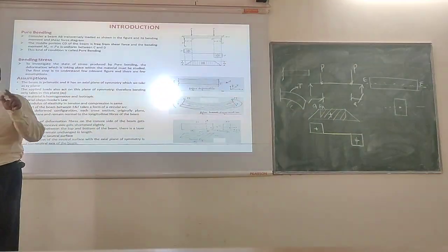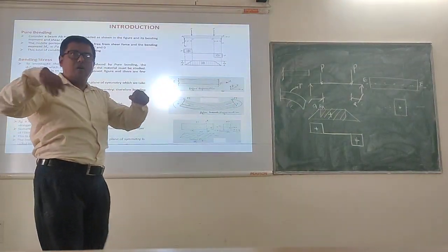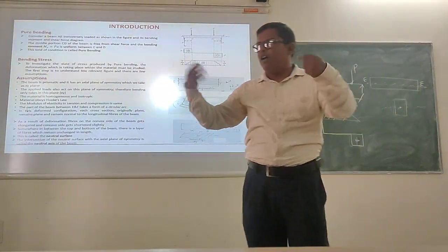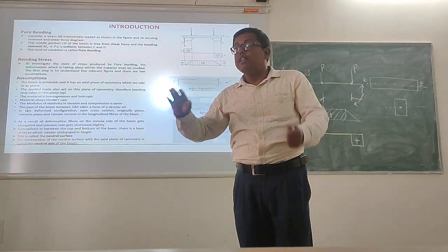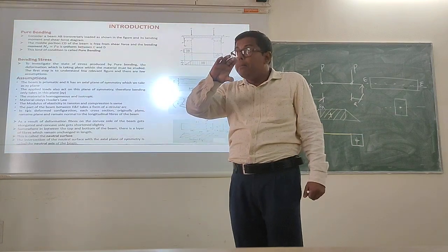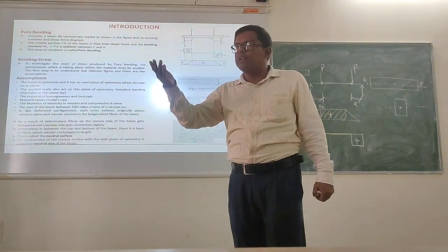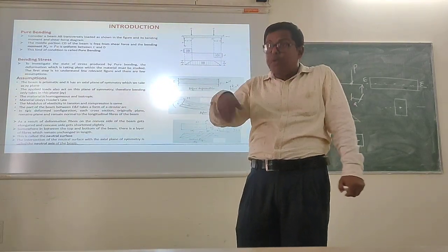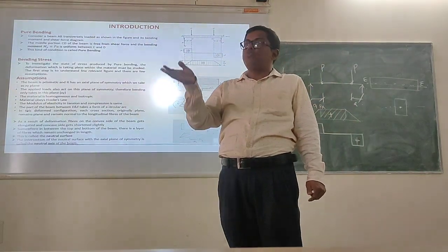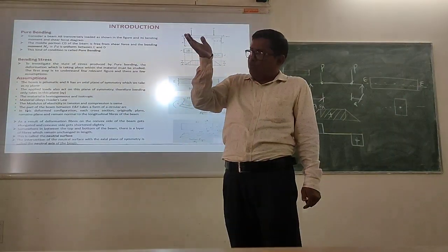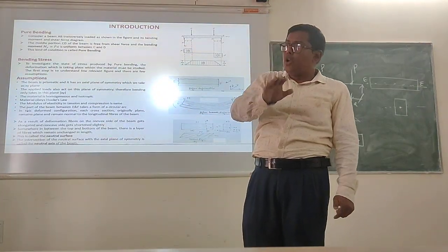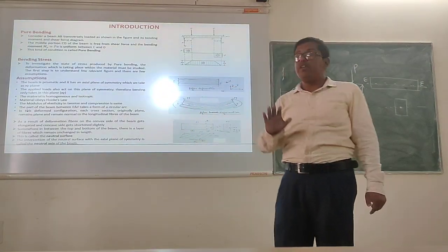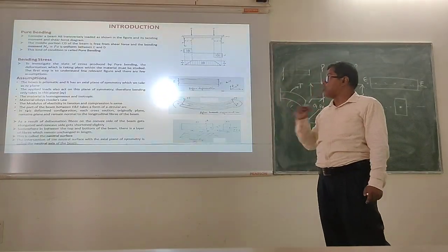When you design a steel structure or you are getting some material like composite fibers and composite structures, then you can say the material is homogeneous. But for concrete, we are assuming that material is homogeneous. We are assuming that it is isotropic. Because to most of the extent, it will be considered as homogeneous. So, assumption here is material is homogeneous and isotropic.